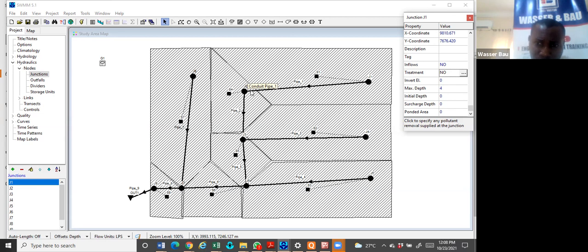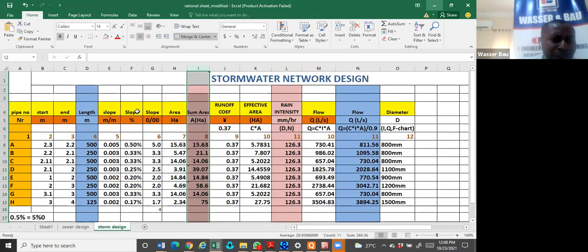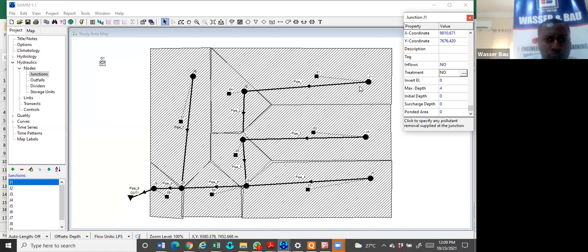Now we have slopes. Now this is very sensitive, and let us get it right. The pipes have slope. Look at them, the pipes have slope, or the catchment has slope. So it means it's not a flat land. And the flow is by gravity. So definitely there must be a gradation from 100 to 99 to 98. Then at the end, you end up at say 95. Okay, so take notes. So here now we're going to use arbitrary slope, but guided by the length.